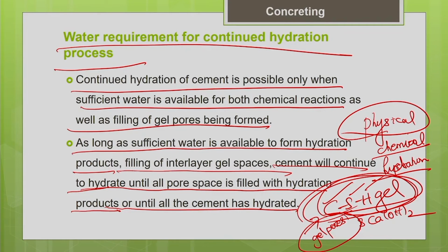Okay. So, this hydration process will keep continuing till the water is available to form these hydration products and till the water is available to fill the gel pores. So, till all the pores are filled, this hydration process will keep continuing, till all the cement is hydrated, provided the water is available.